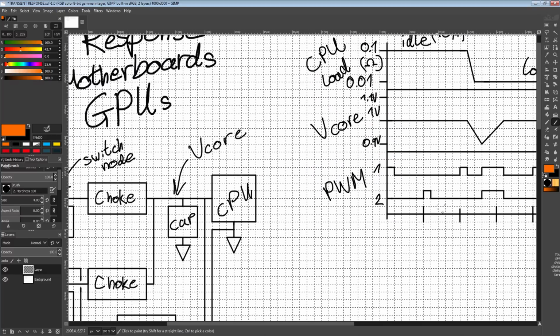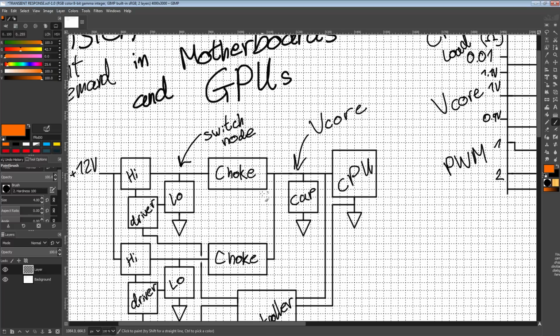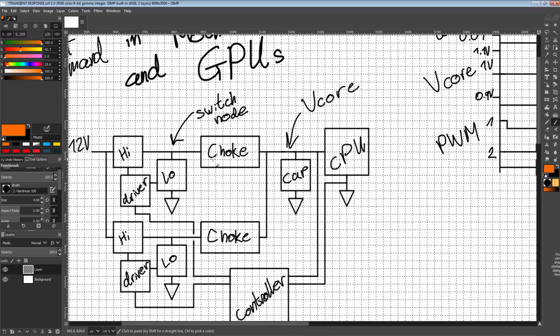And the reason why this is a real problem is because in between pulses, all of the current flow through our VRM, or, well, the current flow through our inductors, we're just going to pretend mostly that the capacitors don't exist, because there's a lot of things happening at the same time, and most of them are related to the capacitors. So anyway, in between high pulses, we're going to have 5 amps flowing through each of our inductors on average.